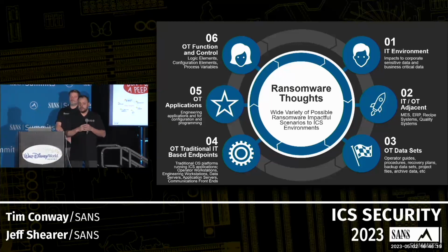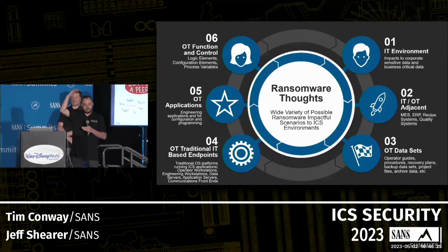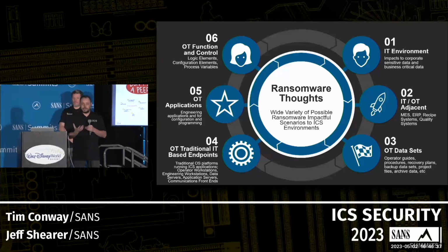We have the option to do something called source code protect. And we can take that entire subroutine or program set within the larger logic, and we can lock that element so that the asset owner and operator can't see how we did it. That is a feature that is not often used, but again, we've asked for it and we got it.